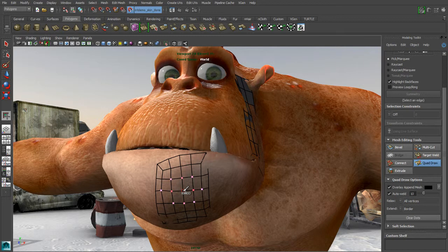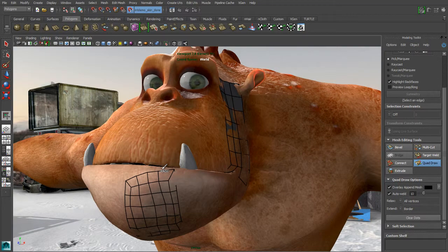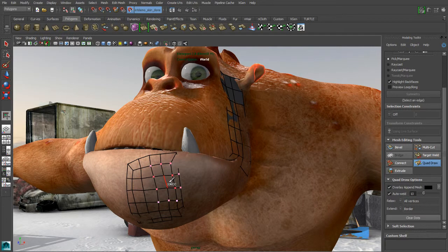So now with that tweak mode, I can effectively grab, based off of my component, I'm using soft selection to adjust that. That's an excellent way to be able to work and edit my mesh on the fly as I go as well. Now, we've taken a look at a couple of different ways that we can tweak, we can relax the mesh, and that we can work with some of the extension or extending some of the edges or edge loops.